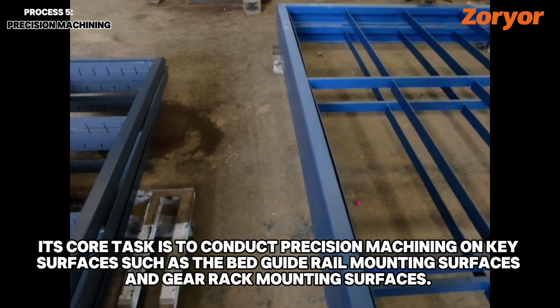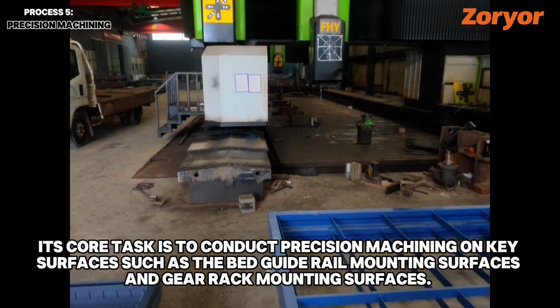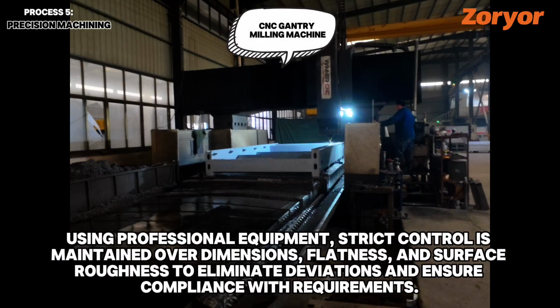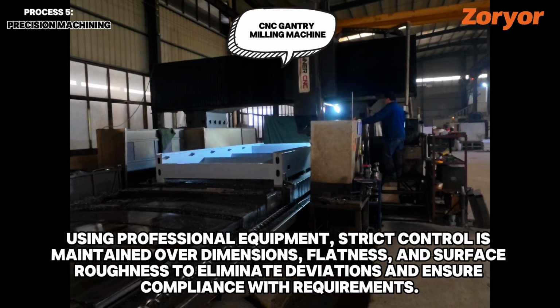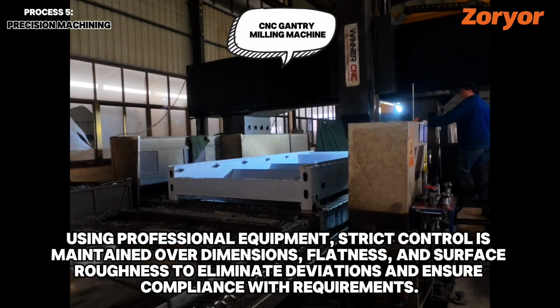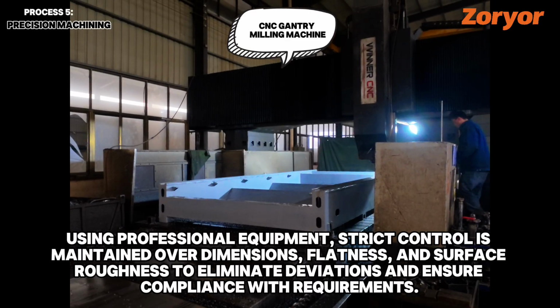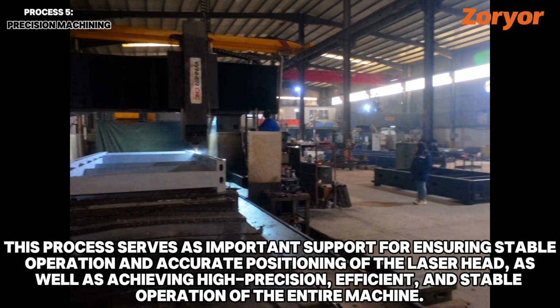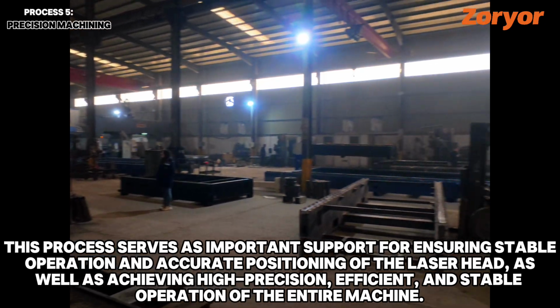Its core task is to conduct precision machining on key surfaces such as the bed guide rail mounting surfaces and gear rack mounting surfaces. Using professional equipment, strict control is maintained over dimensions, flatness, and surface roughness to eliminate deviations and ensure compliance with requirements. This process serves as important support for ensuring stable operation and accurate positioning of the laser head, as well as achieving high precision, efficient, and stable operation of the entire machine.